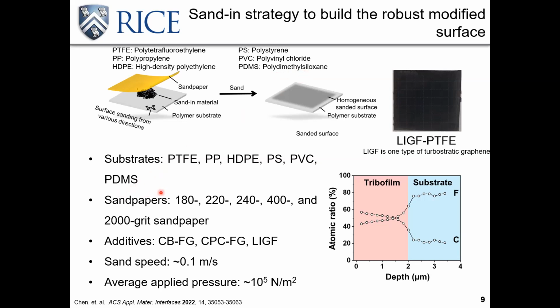We have also tried to use metal to do the same thing here, but we might need to change the sandpaper to another material, because the strength of the sandpaper we used might not be good enough. And for the case of glass, we think by changing to a different sanding paper like silicon carbide, we can use a similar method to functionalize the glass too. That would be a good experiment to do if you can modify the glass too.